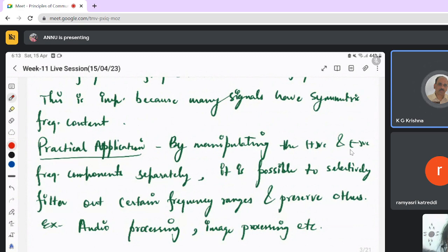If you wanted to represent it in the time domain, it is continuous, extending from minus infinity to plus infinity, periodic. To represent it in the Fourier transform, it becomes symmetric around the y-axis at plus fc and minus fc, but with amplitude equally distributed, A by 2 and A by 2. Correct?